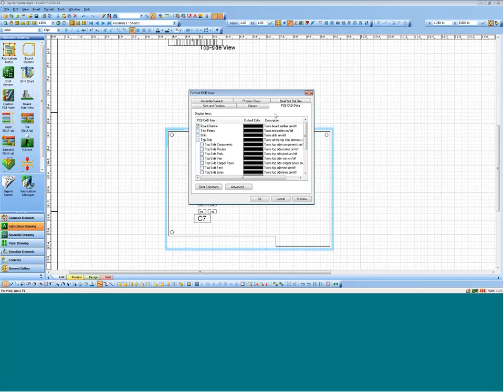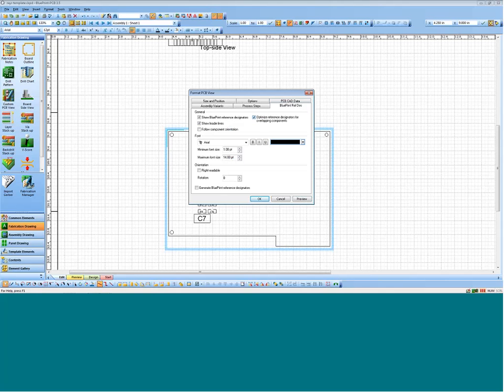This was the PCB CAD data on which information you're showing. There's also some other things we can show in here. One of the nice things we'll do for you in BluePrint is help you with reference designator cleanup. Oftentimes your assembly layers are more reflective of the silk screen than actually something that's usable for doing assembly. So what we'll do for you is we'll allow you to set a minimum font size, a maximum font size, what sort of font you want to use, and actually create the reference designators for you centered in the component outlines. And that helps you clean up the reference designators.